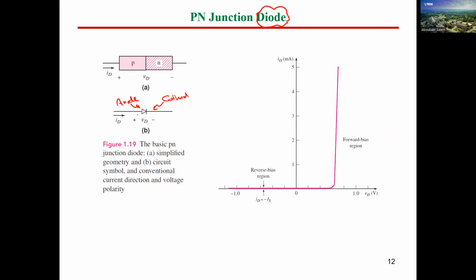For that, guys, in order to turn on the diode, we mentioned that VD has to be greater than V barrier, which is semiconductor dependent, could be 0.4, 0.7 according to the material. And once we have VD greater than V barrier, this means the current will flow. So for instance, guys, current starts flowing here from this point. All of these places have very little current, which is the saturation current, a very small value. And once VD is greater than V barrier at this point, a current will start flowing, as you can see. Here, this is a small diode current. As you can see, the current range is in milliampere. But later on, we will see higher values of current.